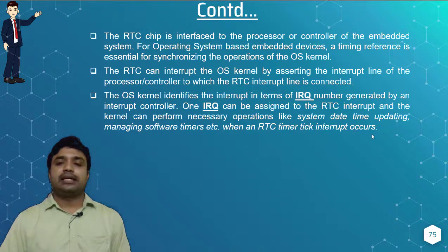That means when the RTC section needs maintenance from the kernel section, based on the interrupt generated from the RTC section, the kernel will perform the necessary operations like system date and time updating, managing software timers, etc. when the RTC time tick interrupt occurs.